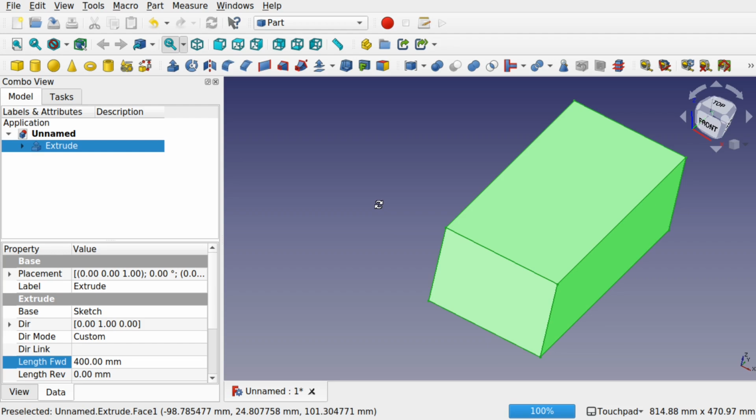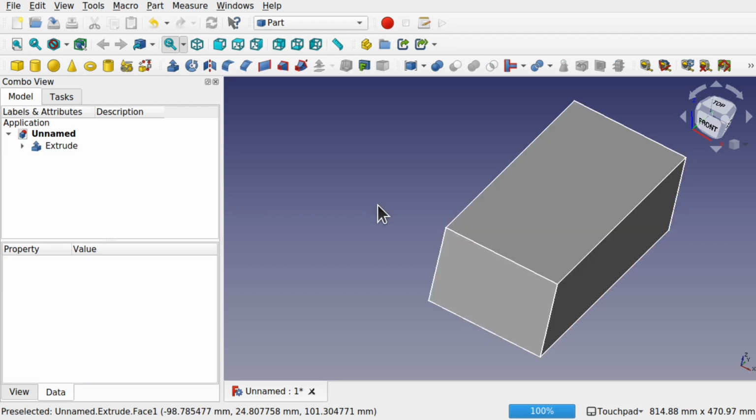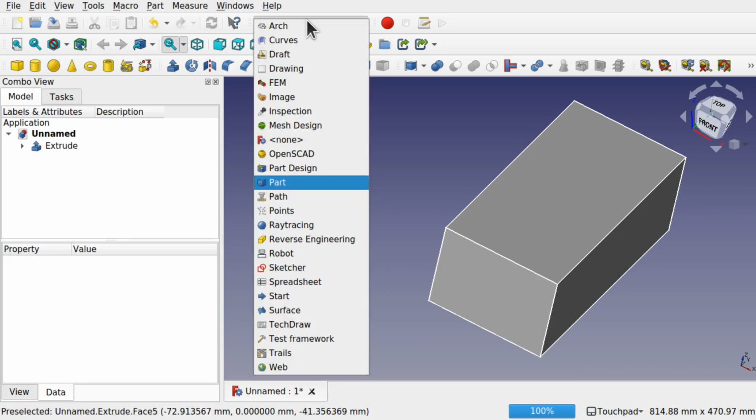When creating the boat itself, when we're lofting that boat, we can't actually use this tool here. We do normally use this tool to create cross sections, but this isn't parametric, so we need parametric cross sections to actually create ribs along the boat. So if our boat was actually inside here, this is going to be our cutting tool. Now how do we do this? Well, this is where the curves workbench comes in handy.